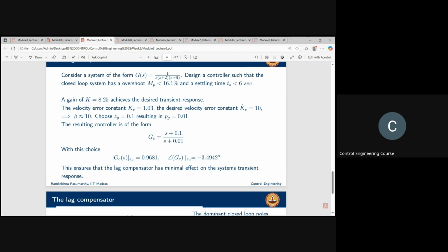Got it? So the root locus of the lag compensated system will start at the pole and end at the zero. There will be a very tiny strip only that starts at that pole close to the origin and ends at the zero close to the origin as well.